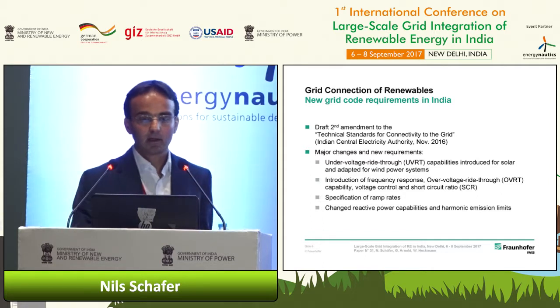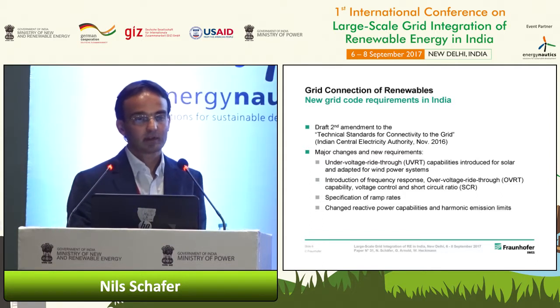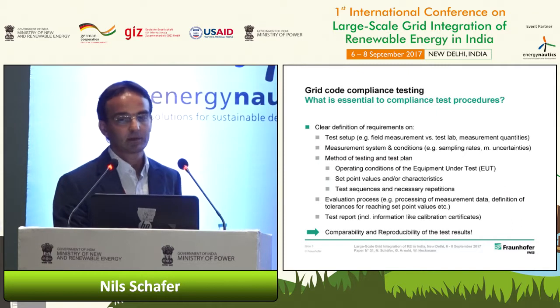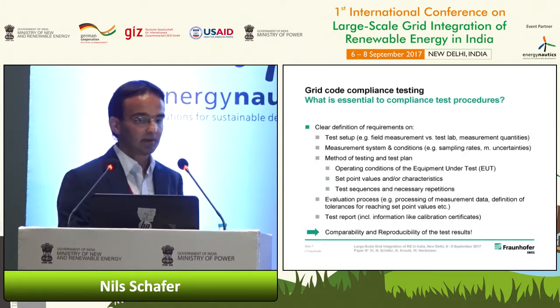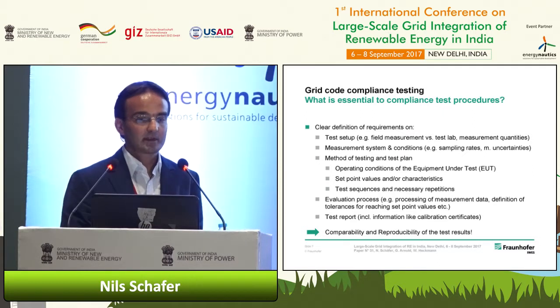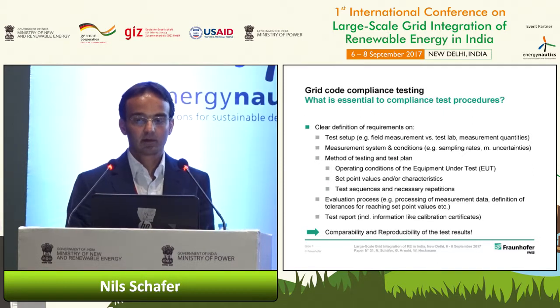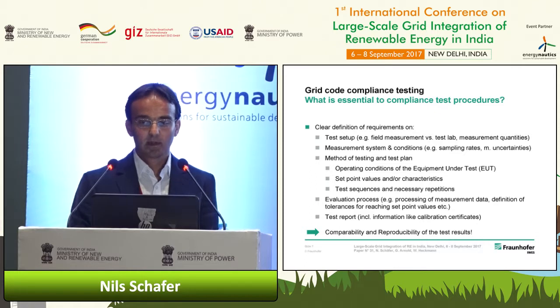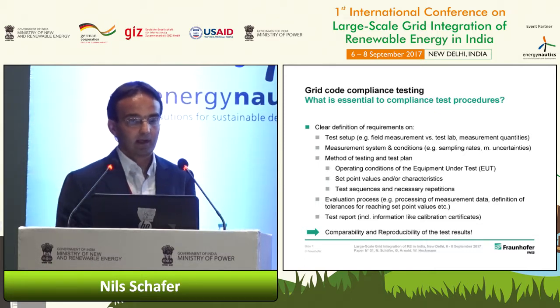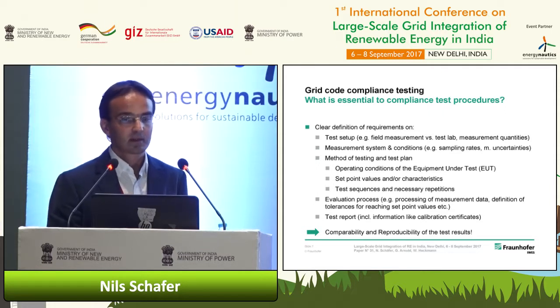So now I come to a major point of my presentation. I would like to discuss with you what is really essential to compliance test procedures. It's important to define clearly a test setup. It differs if it's a field measurement or if the test is done in a test lab. You have to define the measurement quantities, how the measurement system shall be laid out, and what the measurement conditions are.